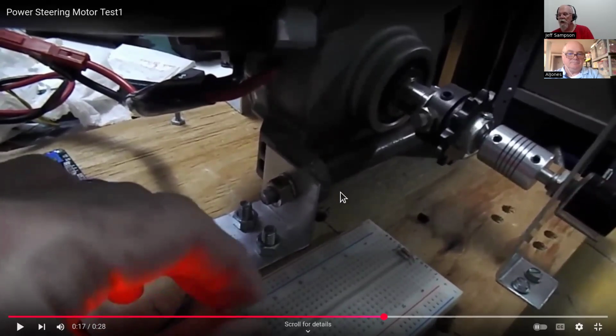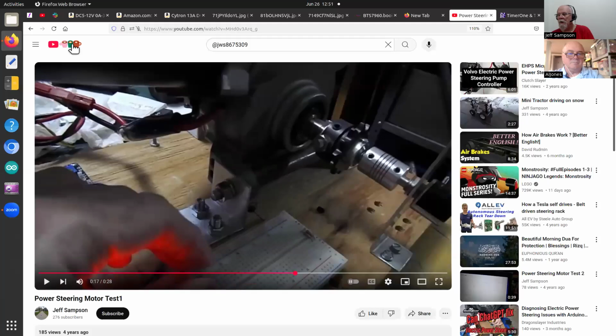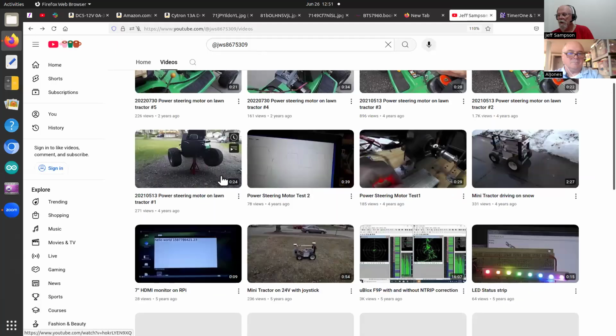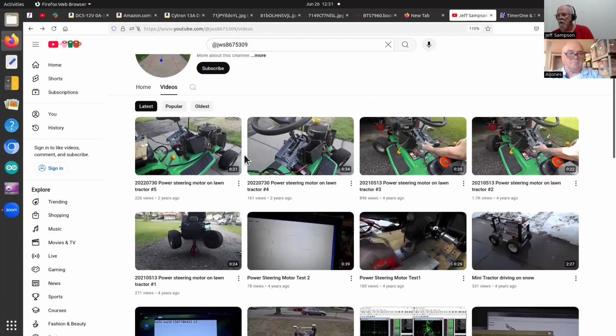So I was telling Al, because he's using the AnalogWrite and he's going to be talking to one of these kinds of motors, I said, well, your motor is going to squeal unless you go to the TimerOne function. He said, oh, what's that? Well, here, let me go one more step here. If you go to the TimerOne function, let's see, back up here. And here's an example of that same motor.